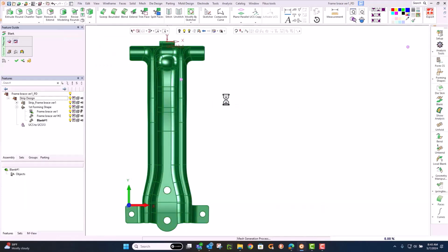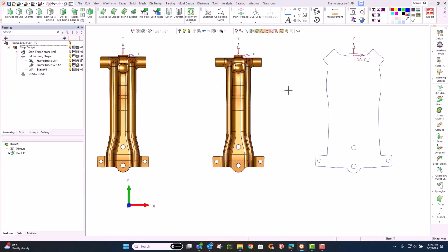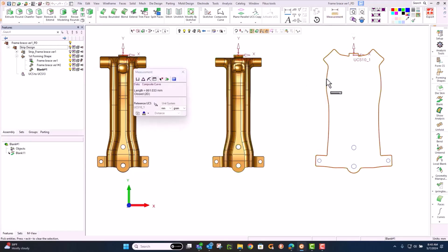Now with this position in mind, we're going to do a crash form, basically an overall quick blank. What are we dealing with when it comes to looking at formability? This allows us to do an FEA analysis where we can check on what areas might wrinkle. Here we're doing a quick check to see on the overall perimeter of the part.